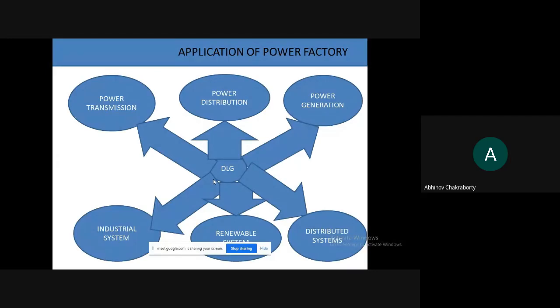If you are going with a very high rating of low voltage unit, you might be using MCCB instead of MCB. Even if you go for higher ratings, you might go for your ACBs, that is air circuit breakers. So these classifications have to be made in a very vivid manner. When I am studying my distribution system, I am taking my distribution system as a whole. I cannot be very specific about the end feeder products at my industrial level.